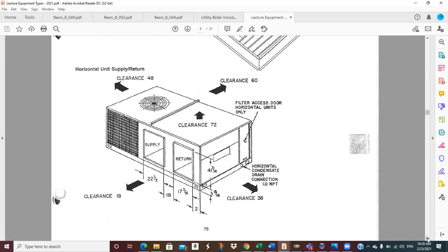I remember sitting there studying these dimensions. Okay, what's the size of that duct? You can do a duct transition, but that unit's going to be pretty close to the wall, and you don't want to do some outlandish transition. So you've got to figure out where you're going to penetrate the wall, what size it's going to be, and what's on the other side of the wall that can accommodate this duct. Am I going into a chase or something? How does that get coordinated architecturally in the building? That unit may have a couple of small units in back, but it's the whole HVAC for the entire showroom and offices and all that sort of thing. So the ductwork has to spread out and go all over the place, and it gets pretty complicated just to make sure that everything's going to fit.